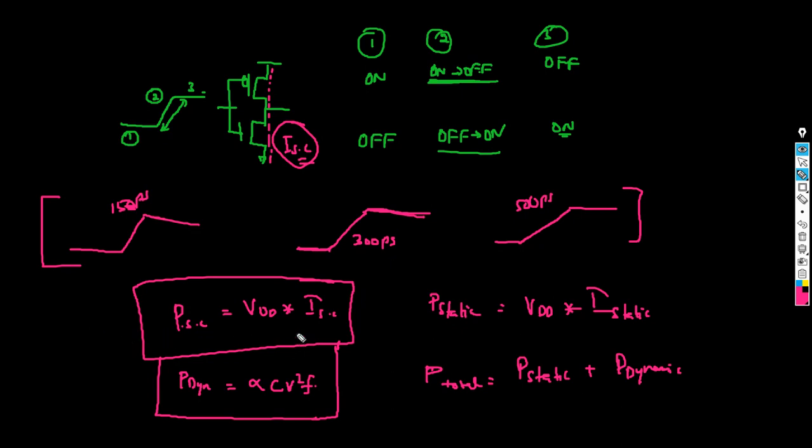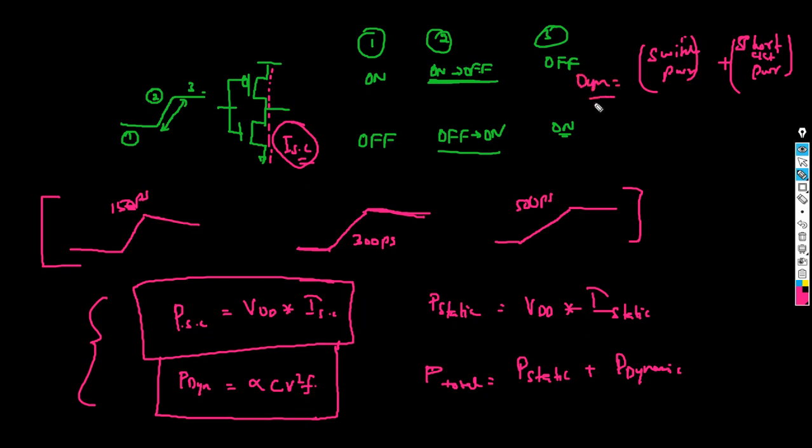Now, the dynamic is going to be both treated together as dynamic power, that is, your switching power plus your short circuit power. Together this is called dynamic. So this is how we calculate your total power consumption.